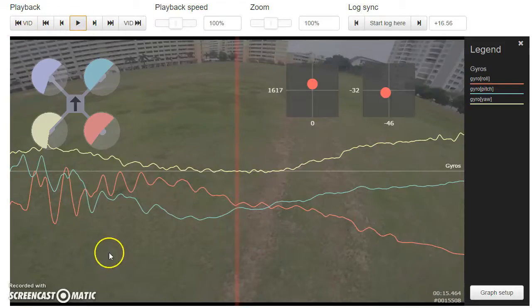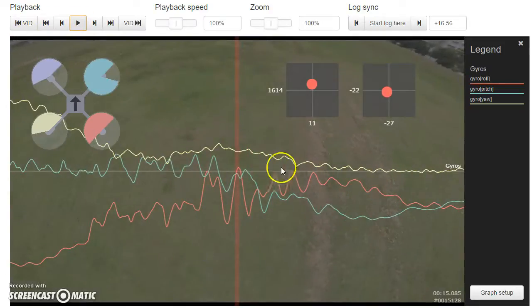But we can definitely see right here those oscillations, and because of the throttle position where they're happening is pretty close to your normal throttle position, we're probably not going to solve this with TPA. Okay, so what axis are they happening on?